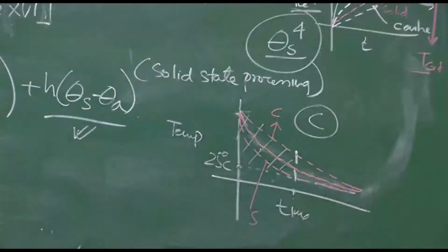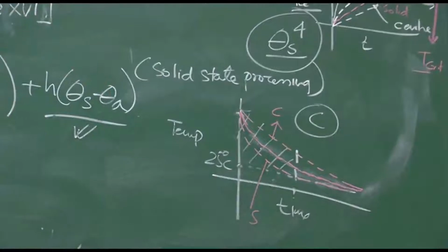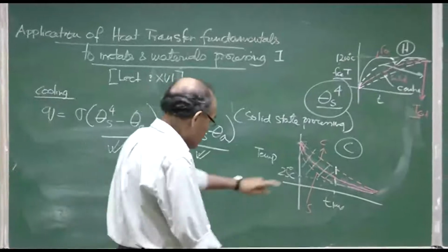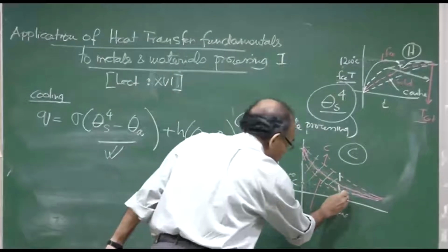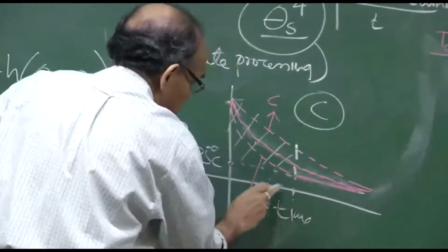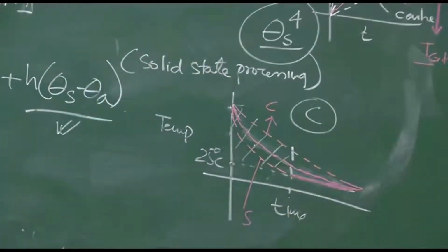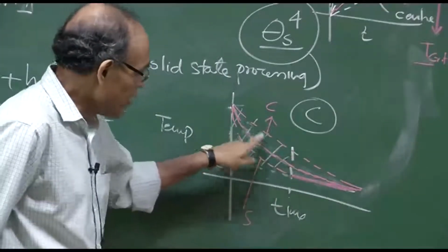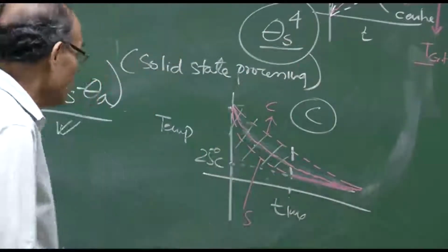This essentially tells that the surface attains steady state with respect to the furnace. The object has not attained thermal equilibrium, but steady state, because the temperature is not changing as a function of time, and that is what I am saying, that it is steady state. Okay? It is constant, equal to 25 degrees centigrade, quite rapidly. On the other hand, the inside of the object is changing at a much slower rate and attaining the ambient temperature at a substantially longer time.